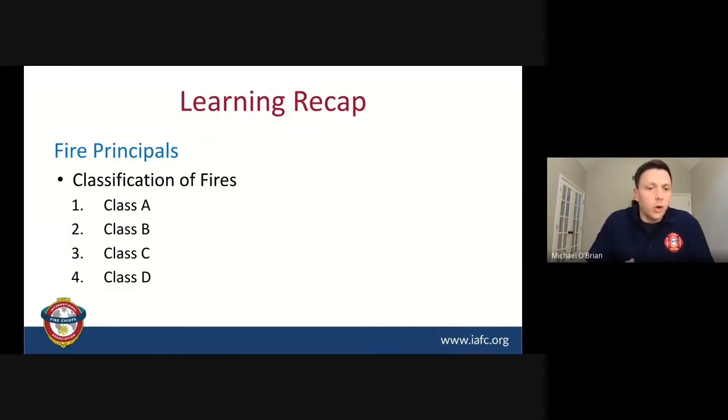So we have early detection. So we talk about those small fires, maybe in that incipient phase, where it activates a smoke detector in a panel and it creates some form of a response, whether it's alerting building occupants, alerting the fire crews, and then we get into even shutting down the power and shutting down the system.